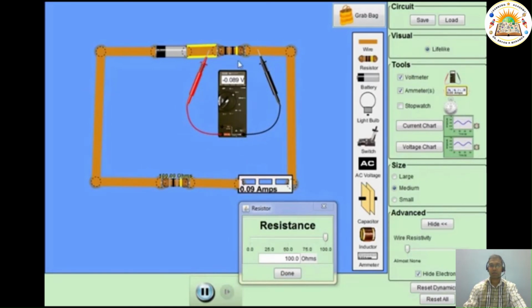So now we will do the same thing as last time. We will keep on decreasing the external resistance to see what happens to the EMF of the internal resistance that is there. So let's keep on decreasing. We can see that the current increases. At the same time, the resistor that is there, you can see what is happening. It is building its own potential. So somewhere around, let's say 1.58 ampere, 4.7 ohm external, 1 ohm internal resistance, we get 1.576 volt as the potential difference across the internal resistor.